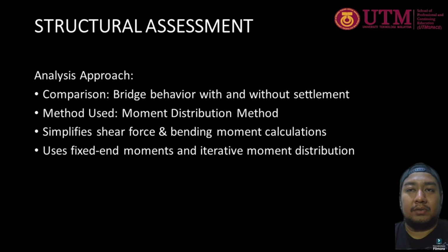Step 3, structural analysis. We analyze the bridge using the moment distribution method to compare the bridge behavior with and without settlement. Step 4, decision on bridge integrity. Based on our analysis, we determine whether the bridge is safe for future operation or traffic should be halted for further rehabilitation.